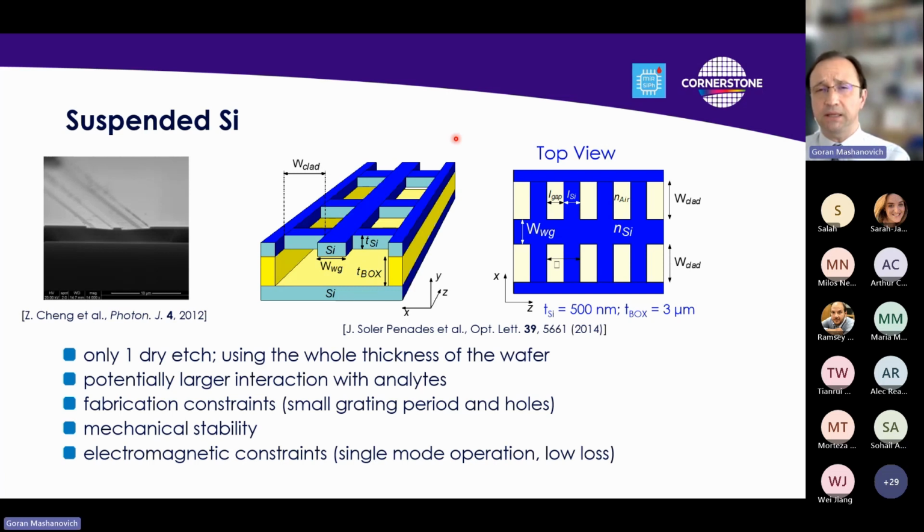So the light basically will see this just as an average refractive index. So we'll get this lateral confinement, and then we can use this hole with some wet etchant to remove, to suspend silicon and to get a suspended waveguide.